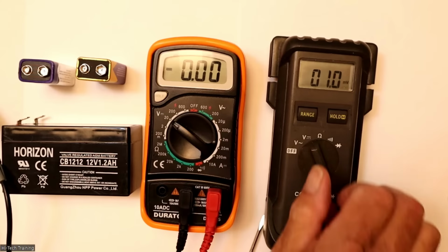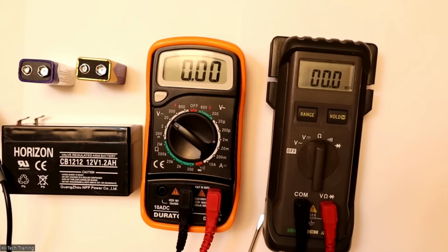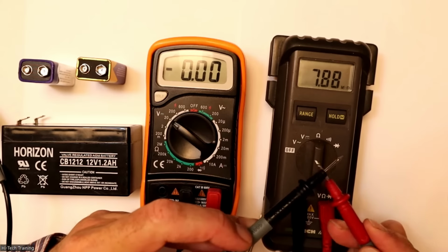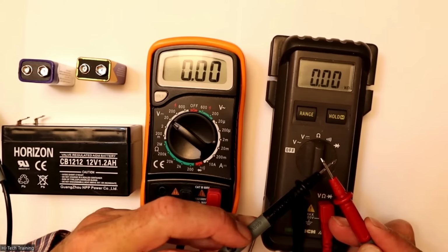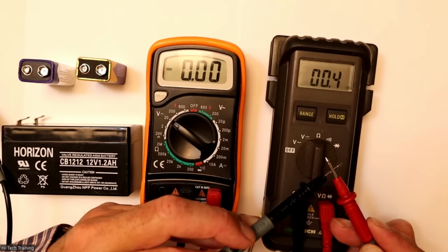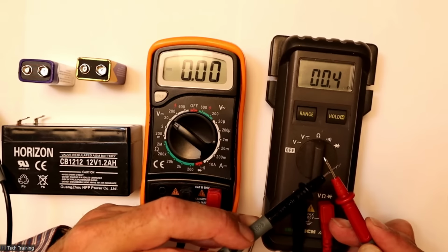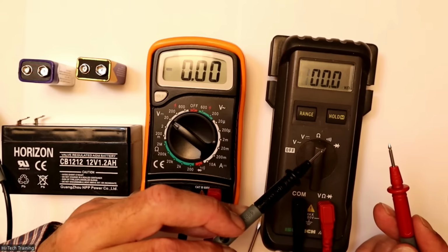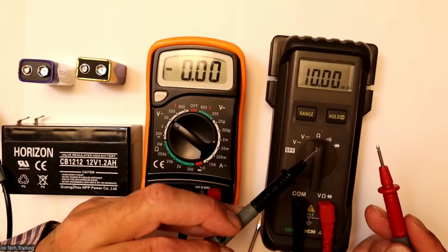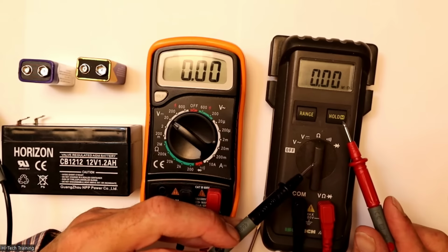I can measure ohms to resistance. So I'll go to the ohms range here and join our 2 leads together there. And we will get, let's see, 0 ohms should be, yes, K ohms, 0.4. It's probably the resistance of the leads of the meter, 0.3, 0.4 of an ohm. If these are unconnected, then you'll read a 1 or OL for that, okay? Mega ohms is reading here.